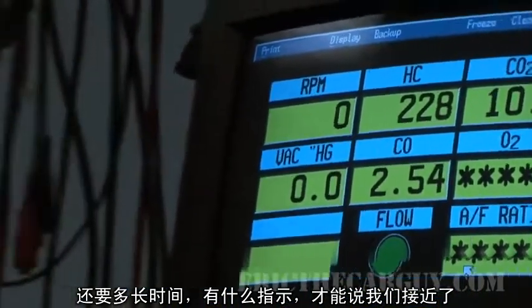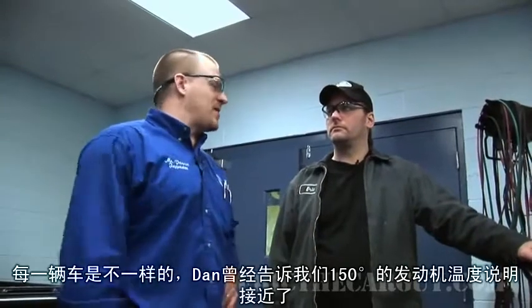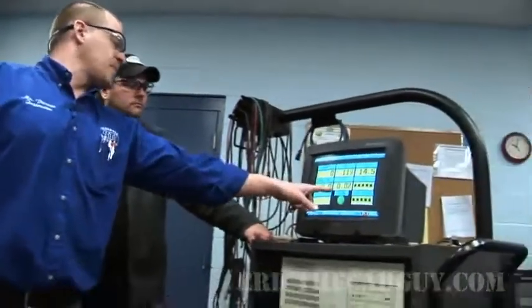So how long would you say it would normally take, or what would be a good indicator that you're now in closed loop? It's going to be different per car. There are some specs out there. Remember, Dan gave us a spec of 150 degrees coolant temperature and things like that. Let that idle. I would say we're in closed loop right now based on these signals, that my CO is very low.